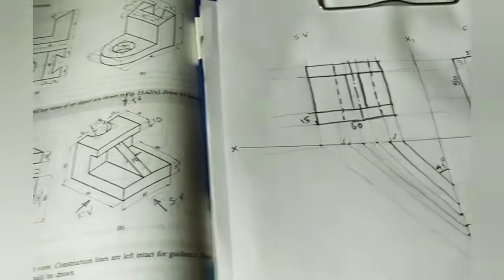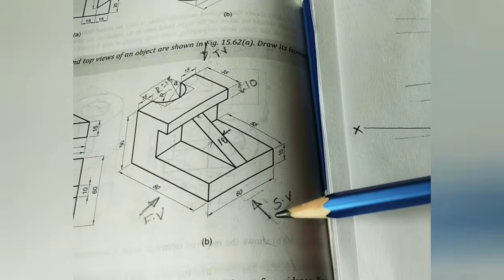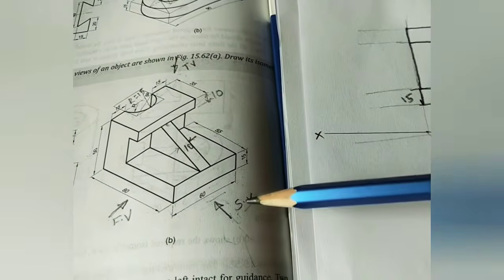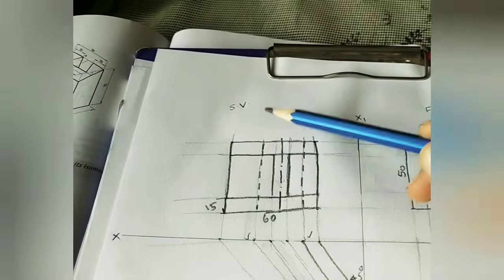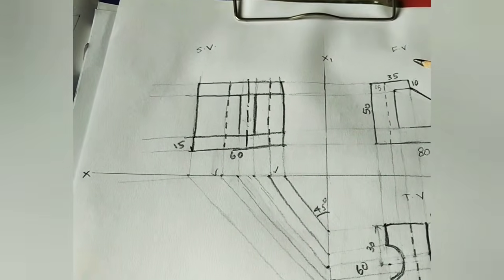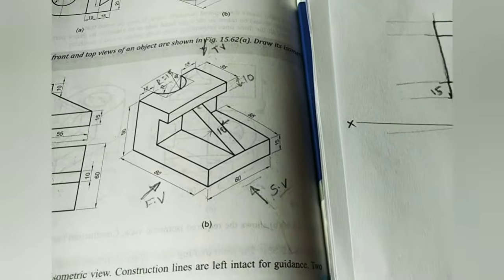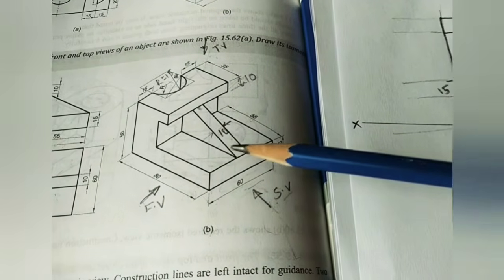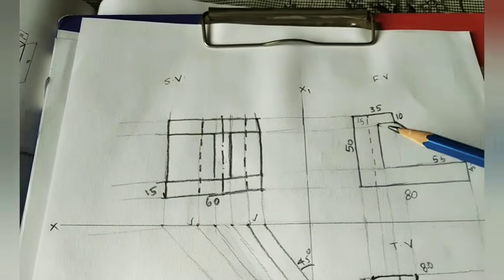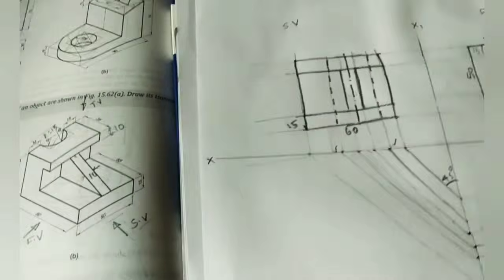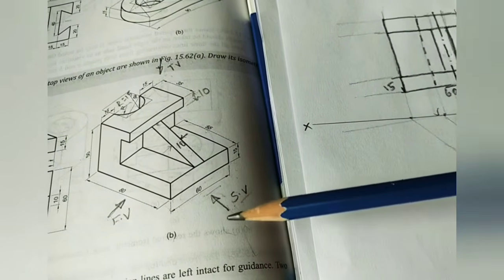Okay, after that I want to tell one thing. Here we are taking this arrow on the right side of this diagram, correct? That's why whatever side view is coming, it is the right side view. This view we can call the right side view also. Sometimes the question may ask to do the front view, top view and right side view. Right side view means the arrow is on the right side of this diagram. But the diagram we are doing is to the left side of this diagram. Okay, don't get confused. Right side view means the arrow should be in the right side position.